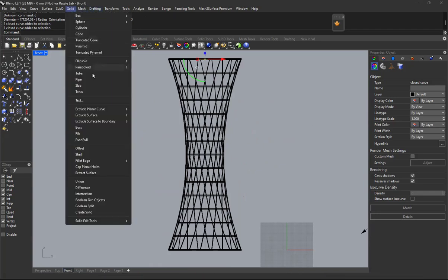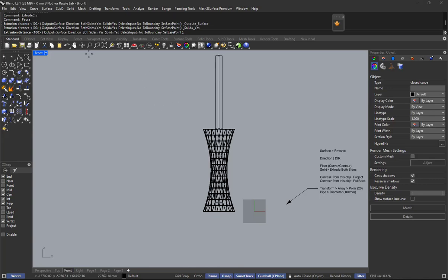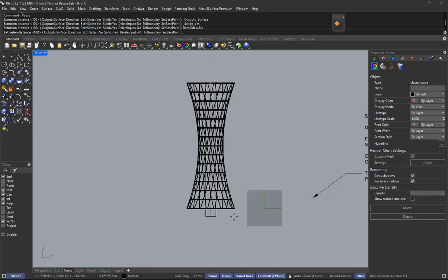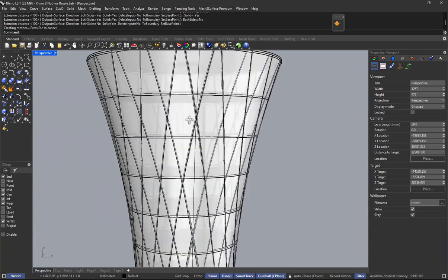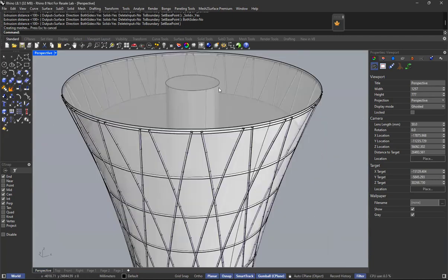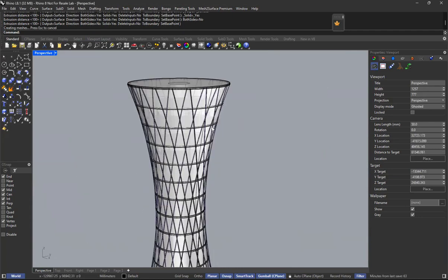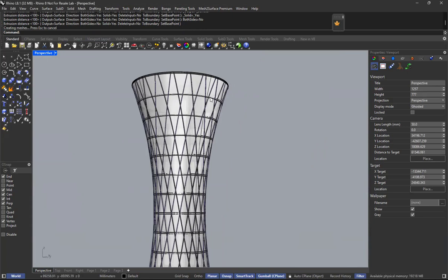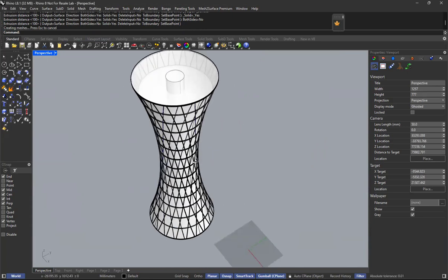We could say solid, extrude planar, straight down. Remember, this is because of both sides. So turn off your both sides at the command. Yeah, just select it and then it will be disengaged. Okay, so I'll say to the endpoint. So let's go perspective. Now we can see this support structure. Okay, so remember to put all of them into different layers. The structure into different layers, floors into floor layers. If you want to say lift shaft into lift shaft layers, you're most welcome.